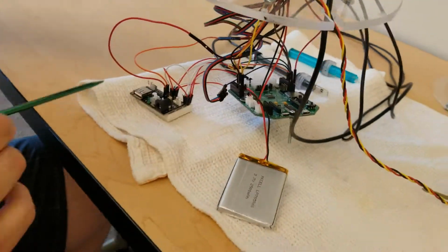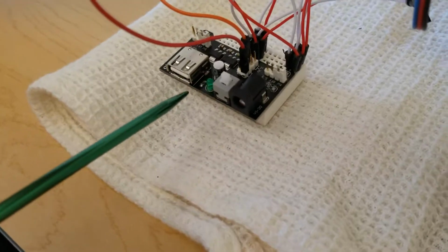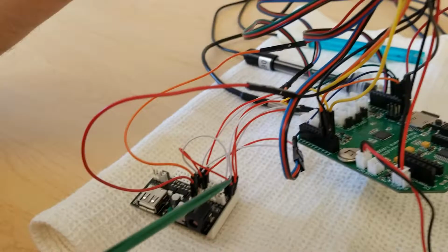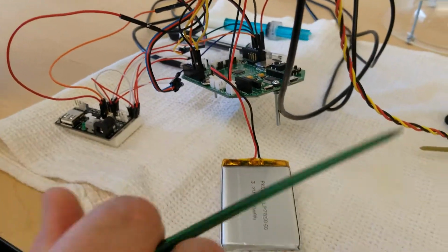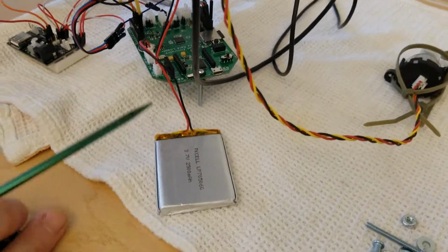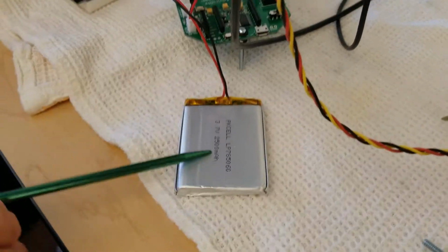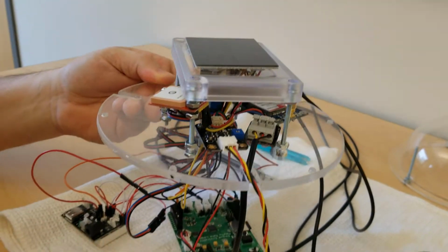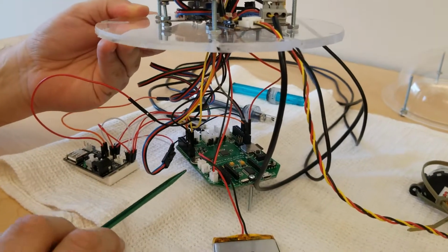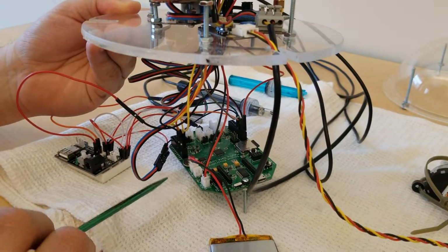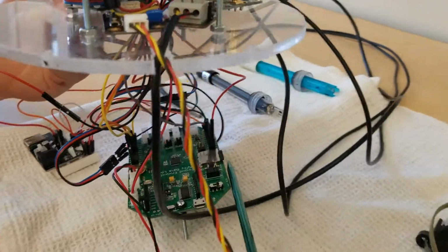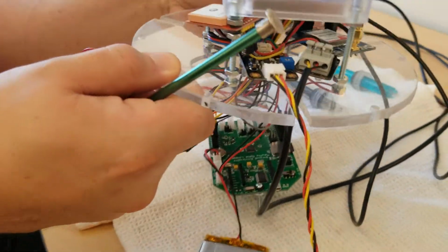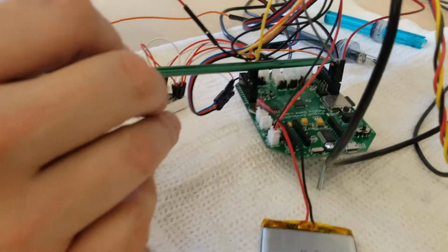We've got a little power shield, and that sends a 5-volt power to all the sensors. This is our lithium-ion battery that powers the main microprocessor. That is charged via the solar panel up top. And in between the two, we've got various things. First of all, we've got the main microprocessor board. This is the Mayfly data logger. It's got a built-in SD card over here that saves all the data readings that we get. All the sensors lead into it via the digital pins or the analog pins here and here.